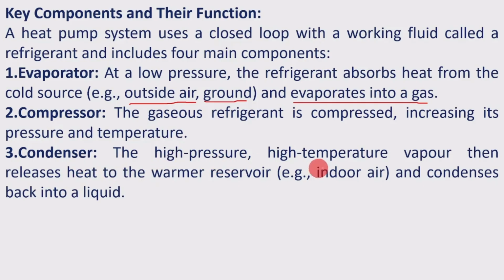The high pressure, high temperature vapor then releases heat to the warmer reservoir, taken as an example, indoor air. That means inside the room the heat is to be transferred, and it condenses back into a liquid after releasing the heat.